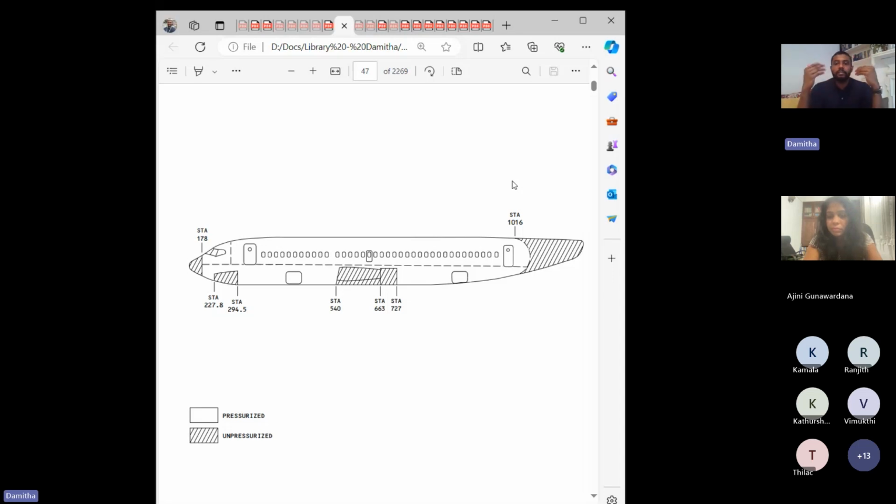It's a physical difference that you can observe. When it's flying at 30,000 feet, the aircraft is pressurized at 10,000 feet altitude pressure. It's not pressurized to ground level pressure. The reason being, it's like a tin container that's pressurized while the outside pressure is low. So it's trying to push the walls out all the time and expand, because the inside pressure is greater than the outside pressure. The whole purpose of the aircraft structure is to keep that in one place without blowing up.